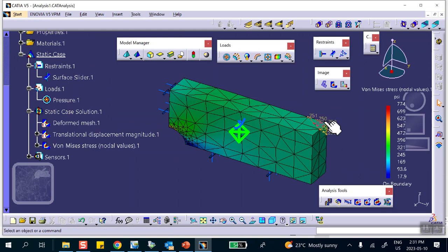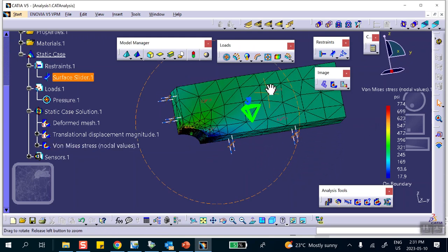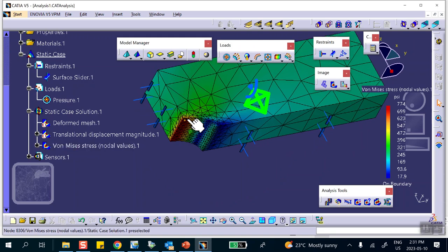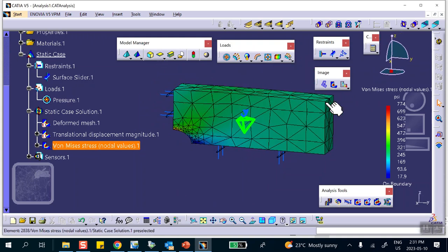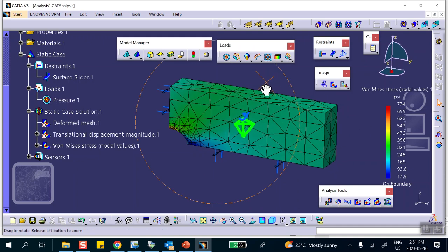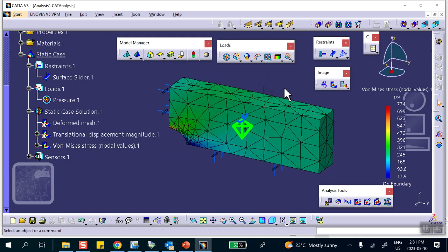No longer those artificial, fictitious displacement at these corner points. And in fact, look at the maximum stress. The maximum stress is right there. The biggest stress is right there. And our intuition says the same thing, because these stresses that were created here were artificial because of the nature of the loading that we put in there. But on the test, of course, if we ask for force, apply force, unless you are allowed to change it in this problem statement. Now notice that this is 774.